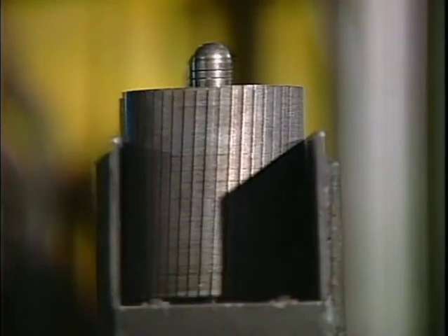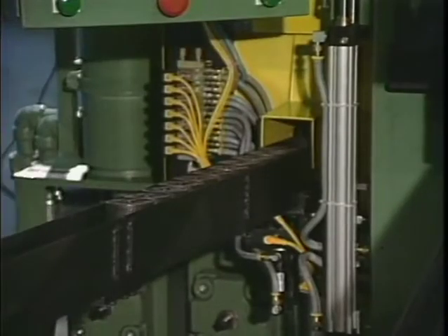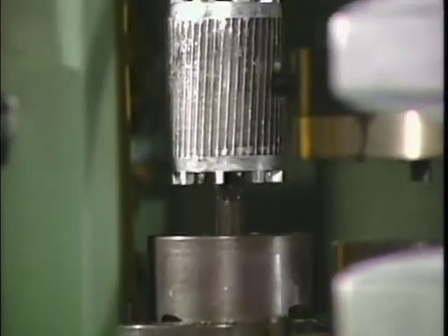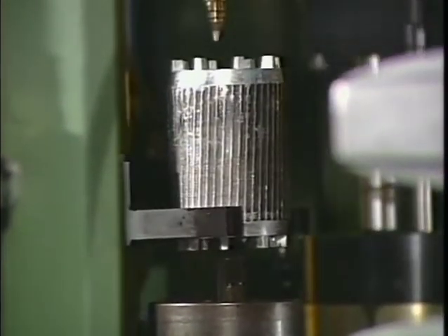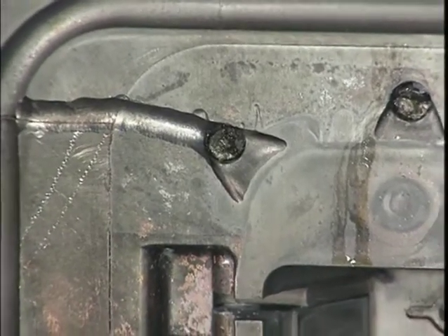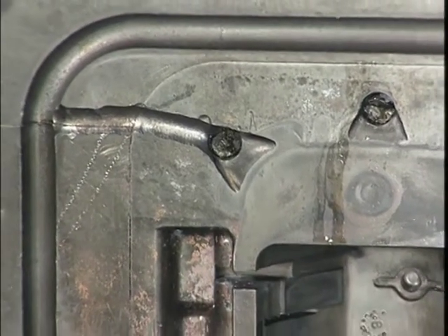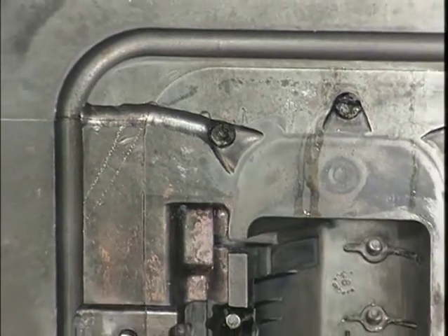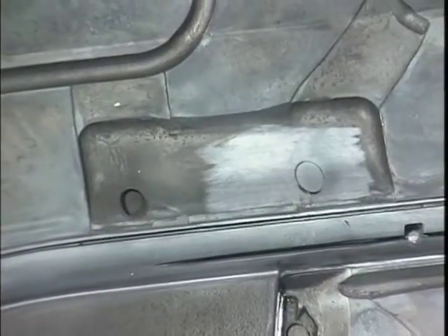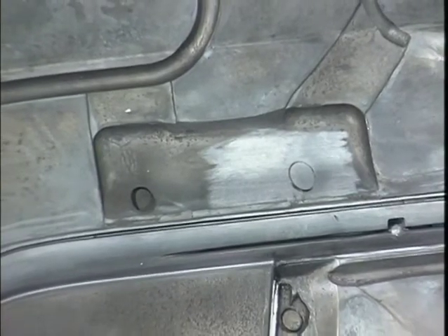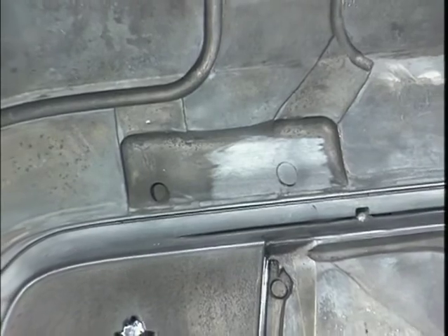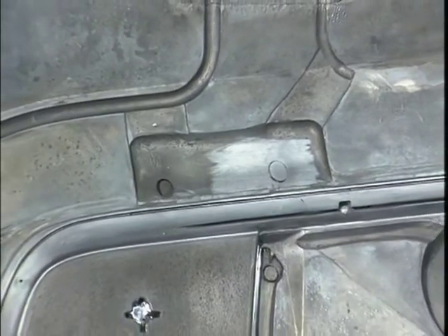Inserts placed in position before each shot also can be used to cast complex features or to be cast in place as an integral casting feature. To minimize porosity in the casting, the die halves have vents to release the air that is pushed ahead of the metal shot. Overflow channels in the die blocks catch surplus metal. They also assist in venting and provide locations off the casting for its ejection.